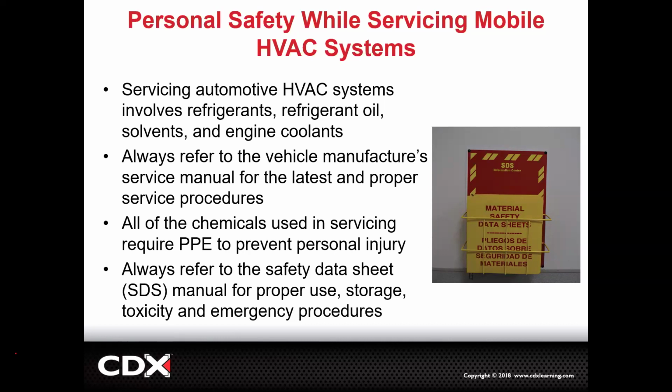So when we're working with HVAC, remember there's some safety things we have to be worried about. And if you're exposed in a weird way, if you really want the facts, you can always refer to the SDS, what used to be the MSDS, just the safety data sheet. It'll tell you about treatment, exposure, all that type of details. So if you're working with R1234yf and you have an issue, all you got to do is look up an SDS for R1234yf. It'll tell you all the protocols depending on what it is you've done. If you've ingested it, I actually don't really know what to do.